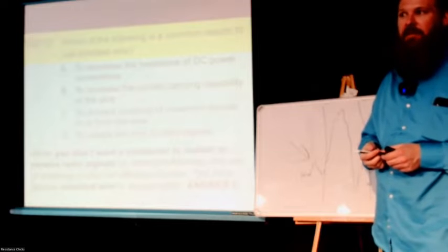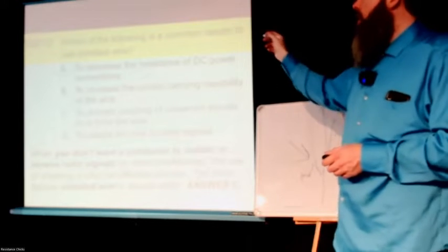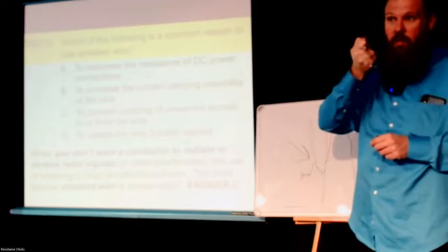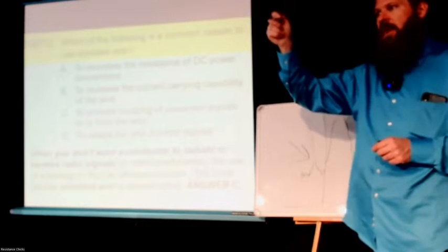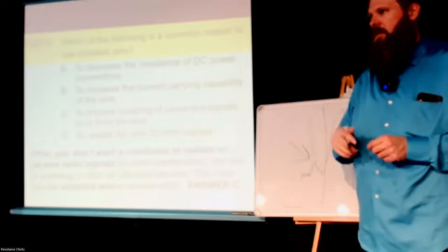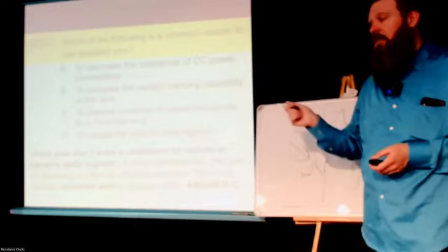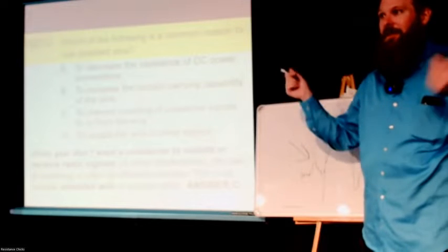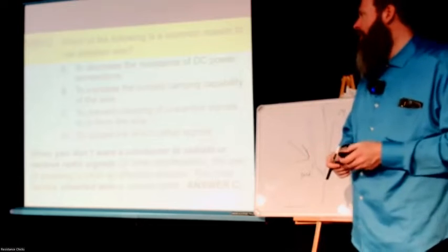How would you fix that? With one of those ferrite chokes. But that's why you would want to use shielded wire. So that shielded wire covers the internal wires that carry your actual voice, and then that shield goes to ground. And so any signal that gets picked up just gets sent straight to ground and gets nullified out. But if you use unshielded wire, then you're using an antenna and it will pick up noise and interference.